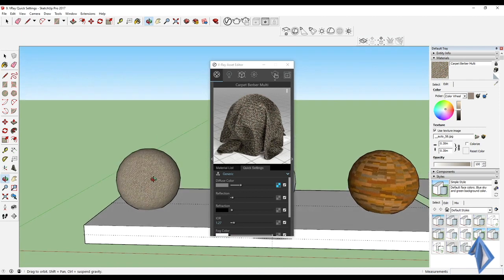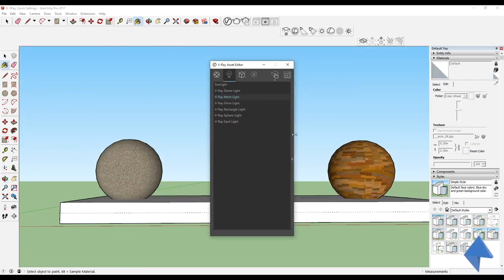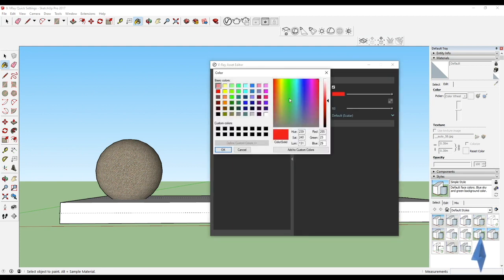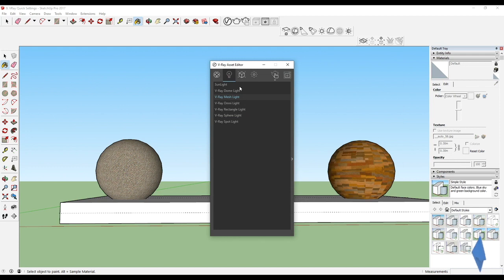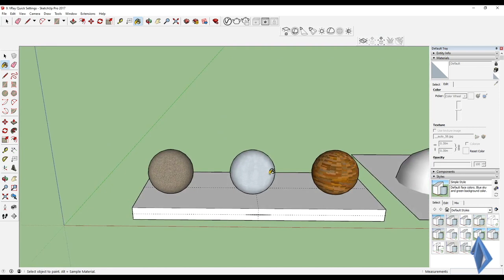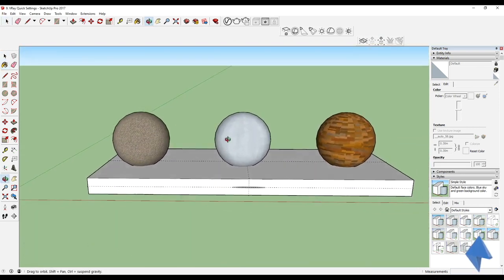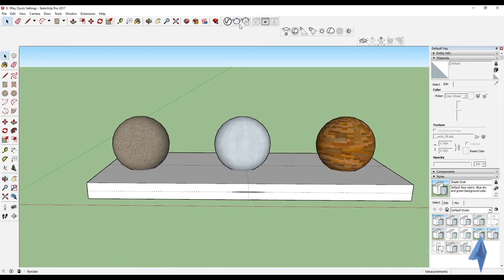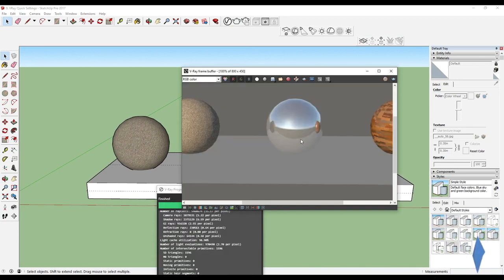Now before I end this topic, I'm actually going to take a render and show you guys how it really looks. Because we have added a mesh light over here, which we have given red color, which is not going to look that good, I'm actually going to change it to white and reduce its intensity. Don't worry about this setting, we'll be getting into the details of it in the coming topics, but let me just show you this. I'll just delete all this off as well, and let's take it for a render. So I'll just hit that render button, and you can see how these are actually looking.